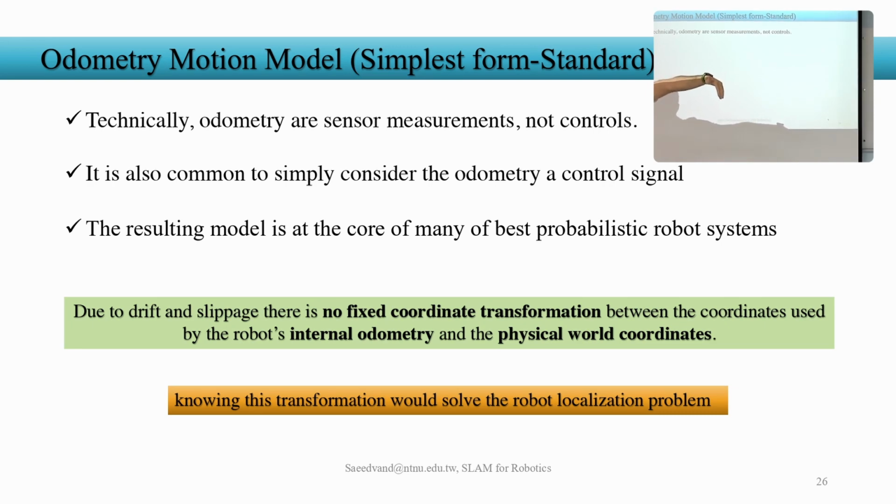This is our knowledge that based on that, in SLAM, we can say, okay, we know that our robot was supposed to move 5 meters. We are expecting that the robot is after 5 meters based on the control command that we are sending. On the other hand, the second element that we have is the odometry reading. This odometry reading reads some values for us and says how much we moved.